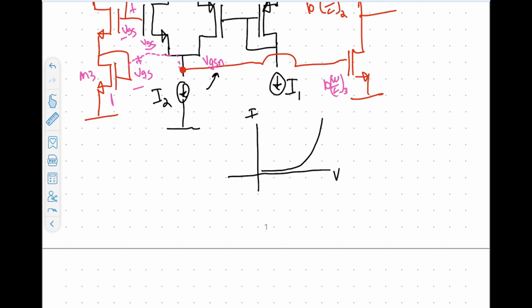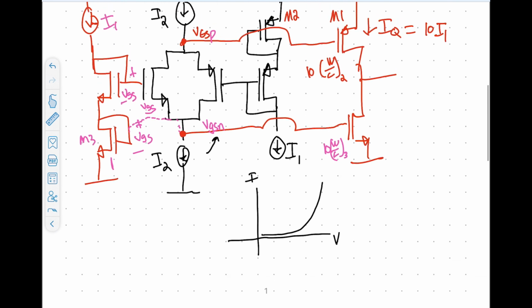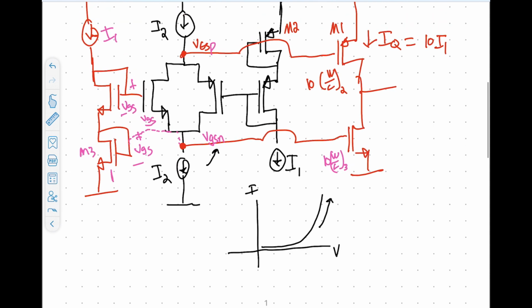And that's, again, highly useful for an output stage, because the other problem that we have with something like a Class A stage is that your maximum deliverable current at the output is a function of how you size the quiescent current, where that is not the case here. You could see that this kind of just goes up. Eventually it'll hit some limit. What that limit will be is the point where this VGSN just won't go up any higher. So we can do that in both directions, and what we get is a curve that looks not like what I drew, but like this.